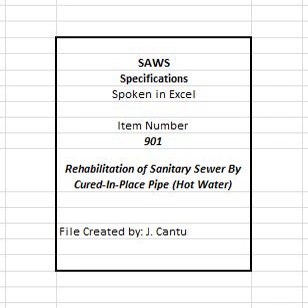901.3 Submittals. The contractor shall submit to SAWS the following specifications, drawings, test results, and other data showing details of the fabrication and installation of the CIPP liner. These submittals shall be considered incidental to this project, unless a specific bid item for such is included in the project bid proposal. 1. Product specifications and technical data for the resin catalyst system, sealing materials, and liner tube.